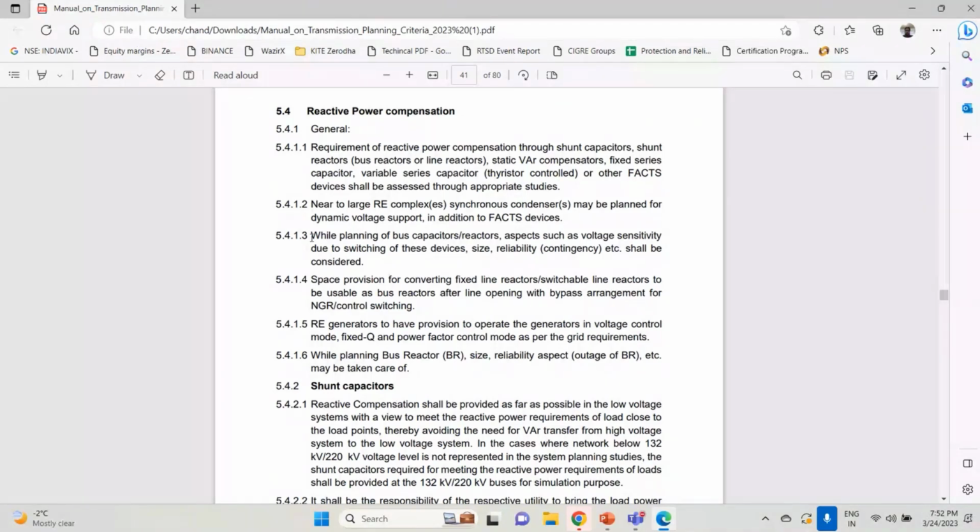You decouple the turbine part, and then you rotate the generator using electrical power. You decouple the turbine because it requires power from the water source, the kinetic energy. If you remove that, it will act basically as a motor. So you run it as a synchronous motor. And then you can control its excitation, right?